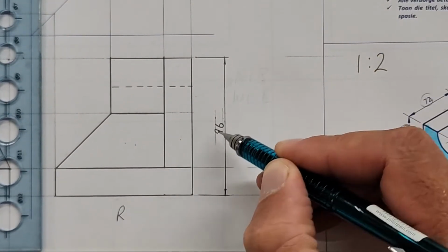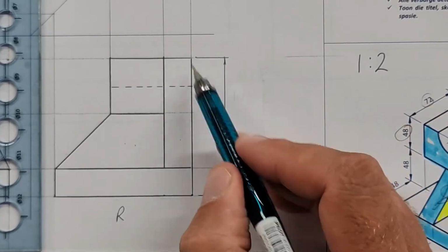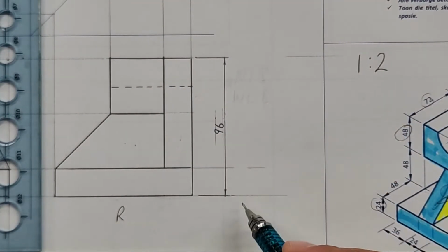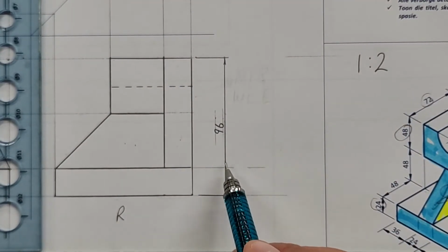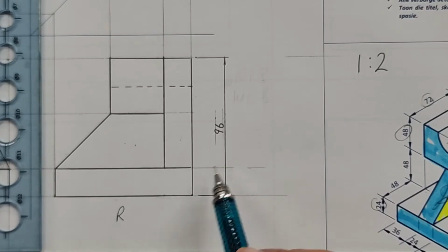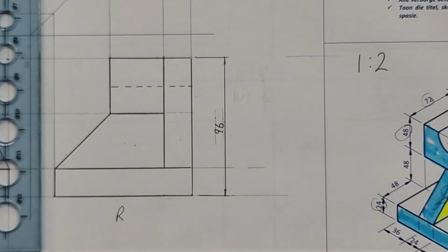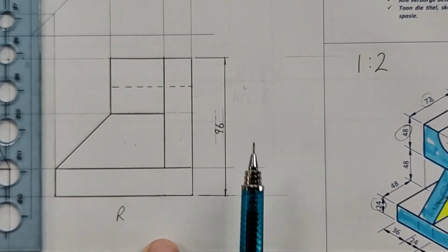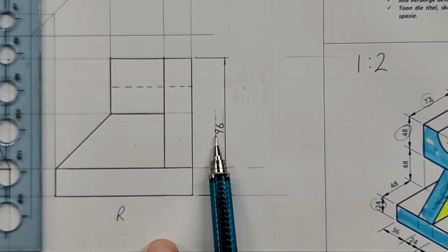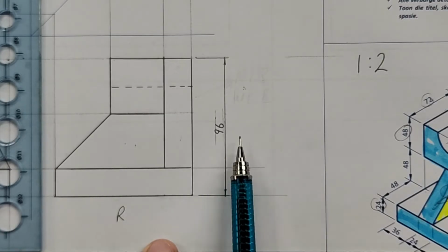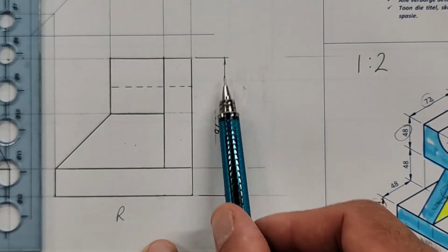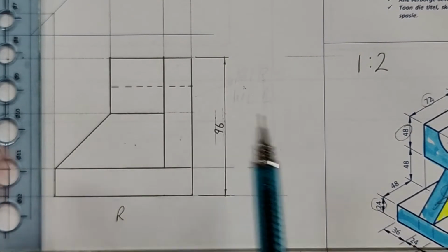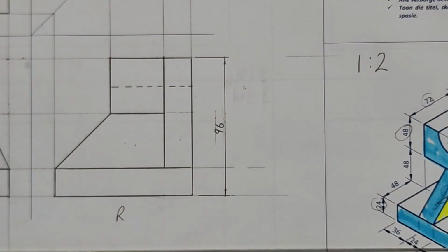I want to see these two construction lines. I want to see that millimeter gap. I want to see the 2 arrows and the gaps here for your dimension lines. And the first one is always 15 millimeters away. Right. Then the next 4. Okay, one more thing. A vertical dimension like this, it's always on the left-hand side of the line. Always on the left side of this dimension line comes your dimension writing. Yes or no? Did you hear me?